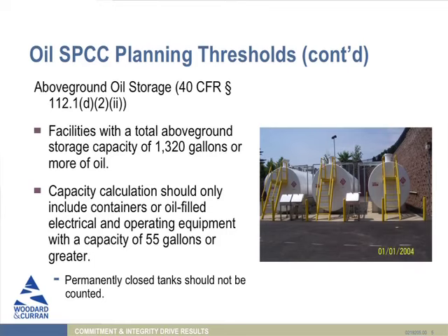Now, wastewater treatment exemption. We talked about this just under the last program, but facilities that are used exclusively for wastewater treatment and not used to meet these requirements are not covered under this plan. And here we're talking about oil water separators, grease interceptors. They're not designed to store oil. That's not their function. It's a treatment process for oily wastewater running through them.